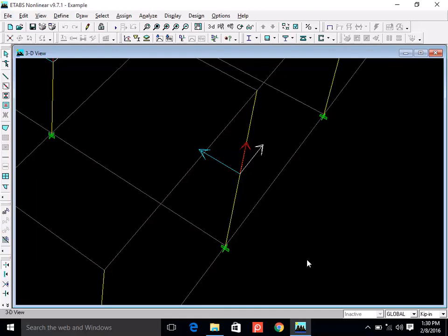Even if you neglect earthquake, for example, look at a corner column. Corner column has biaxial bending. Now biaxial bending means moment about axis 2 as well as moment about axis 3. So both axes become relevant, so shear force as well as bending moment.